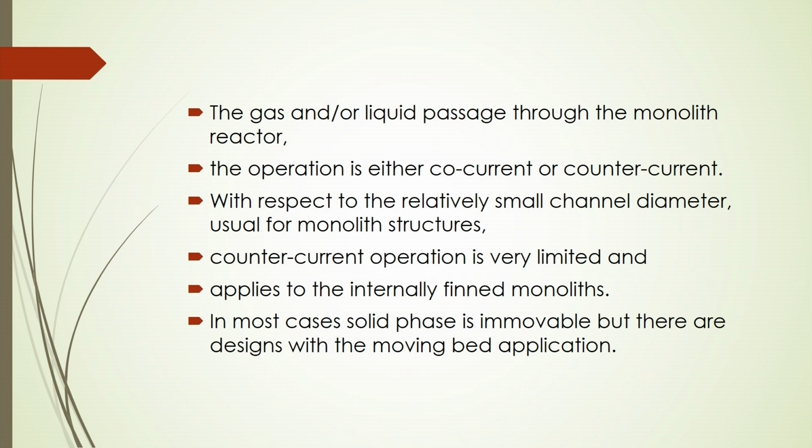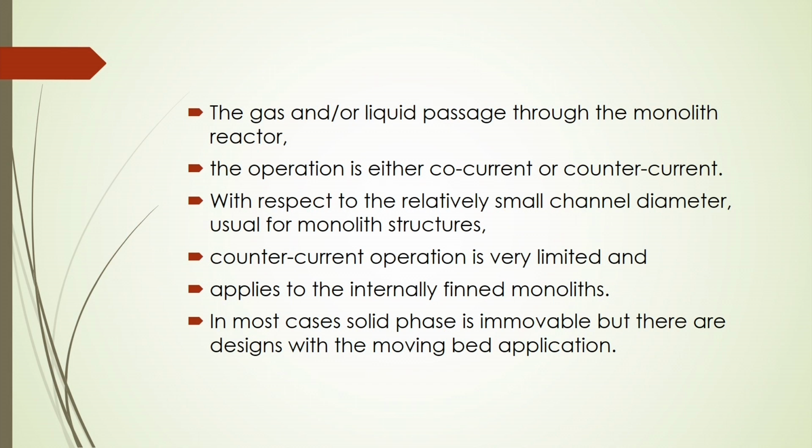With respect to the relatively small channel diameter, you can use this monolithic structure, and for counter-current operations the monolithic structure will be very limited, because it is very difficult to get counter-current operation of gas and liquid in the monolithic structure, because the channel size is very small. So, it is actually very convenient to get co-current operations of gas and liquid, whereas in most cases the solid phase is immovable, but there are designs with moving bed applications also.